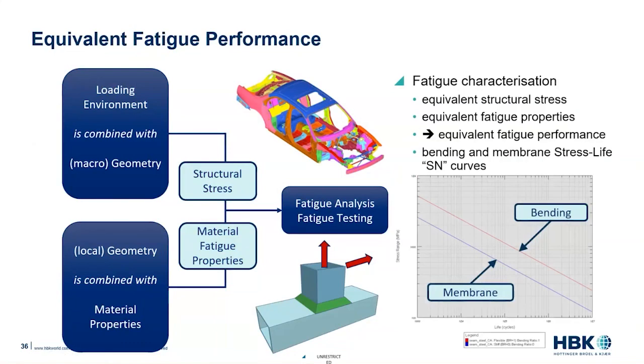The way that this is done is by developing two stress life fatigue curves, one for bending and one for membrane or axial stress.